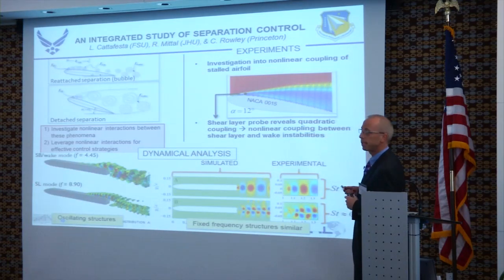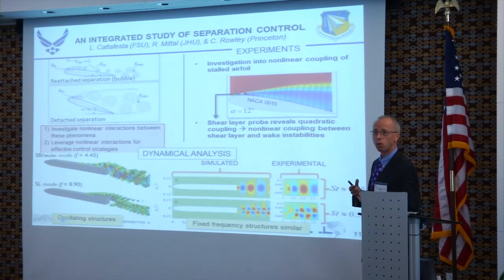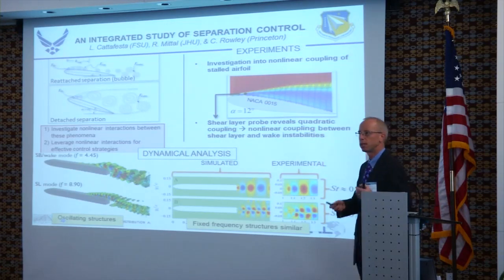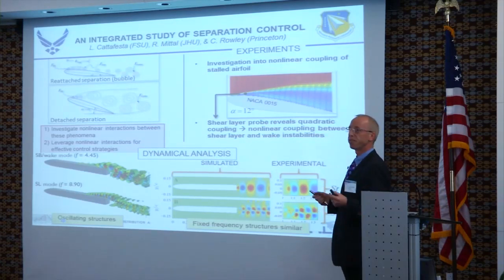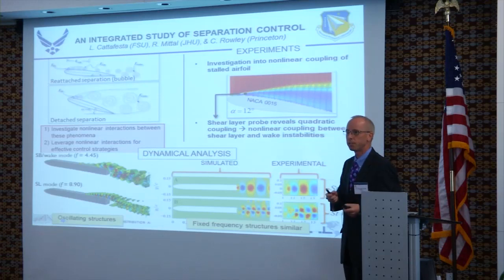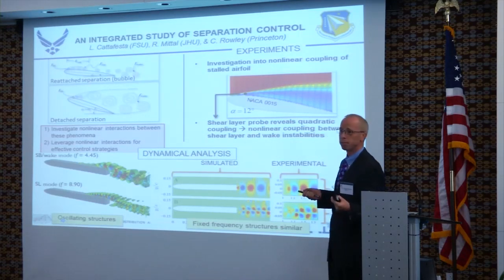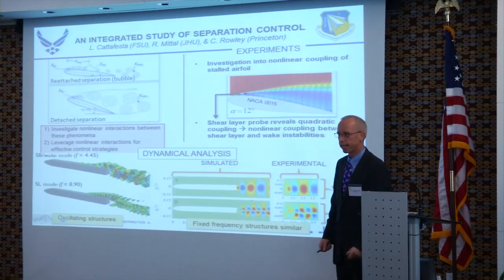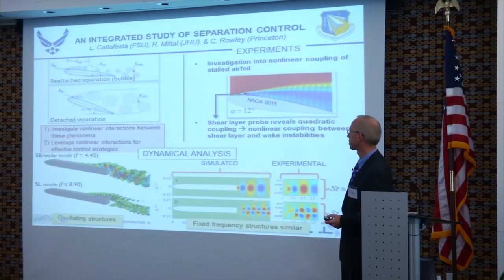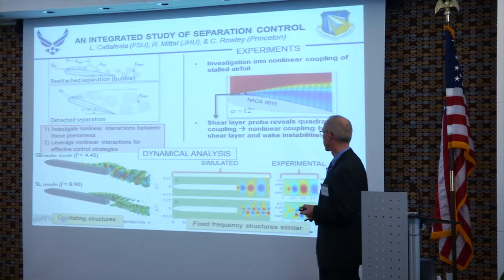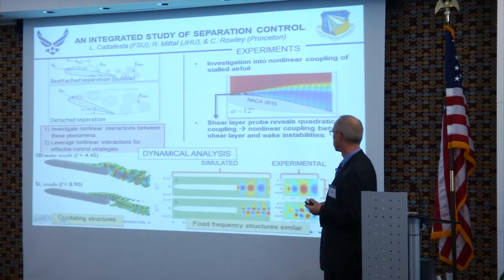Clancy's been great in that he's really helping move the field forward in understanding how to do good dynamical systems modeling of these flow fields. We used to just do proper orthogonal decomposition and then say, all right, we'll do a projection and hope it all works. What you were finding is that you really had to be savvy about which modes you took out of your decomposition. That savvy usually meant putting a grad student in the lab and saying, figure out which ones give us the correct dynamical systems behavior. That's very time consuming and not very intuitive. So they're looking at different ways of modeling.